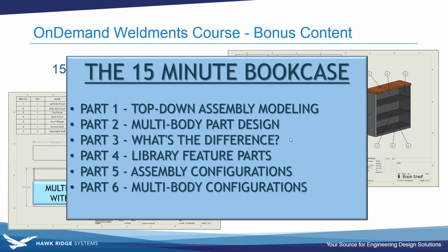And it outlines the benefits that you get with using the weldment feature in a multi-body part and the cut list, as opposed to bill of materials. It all depends on what your output needs to be. That's design intent, all right?